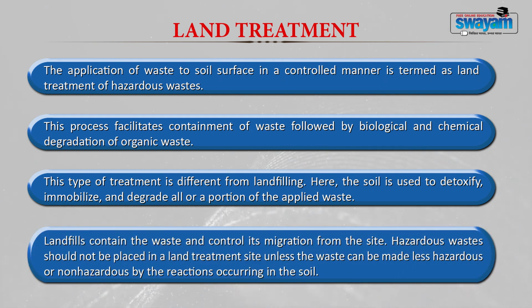Now, a landfill contains the waste and prevents the migration of any pollutant to the outside environmental matrices like soil, air, water and so on. A hazardous waste should not be placed in a land treatment site unless the waste can be made less hazardous or non-hazardous by the reactions which occur in the soil.